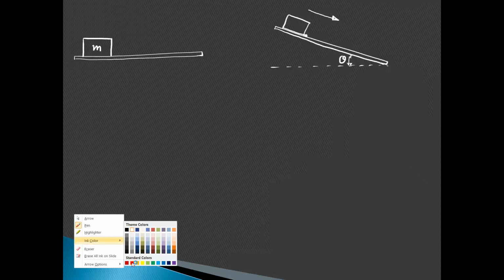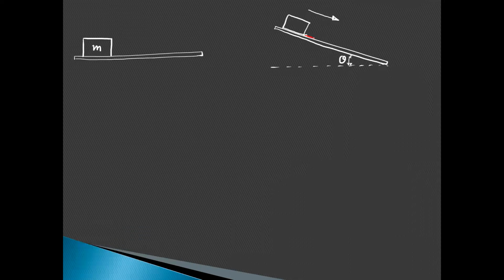The meaning of verge of motion is that the object has a tendency to slide down the plane. Verge of motion is such a condition that at this point the frictional force developed will be the maximum friction, which is called the limiting frictional force.